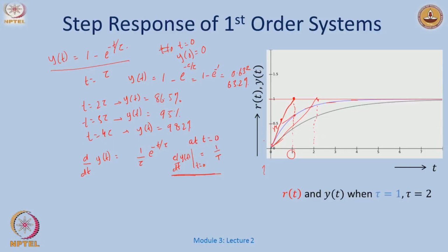And if you look at the slope, it also decreases monotonically as t goes to infinity, until it reaches a slope of 0. Okay. Now what about these guys here? How would I say that I have actually reached some kind of steady state value, right? I do not have to wait till infinity. So I will slowly define a term now called the settling time.